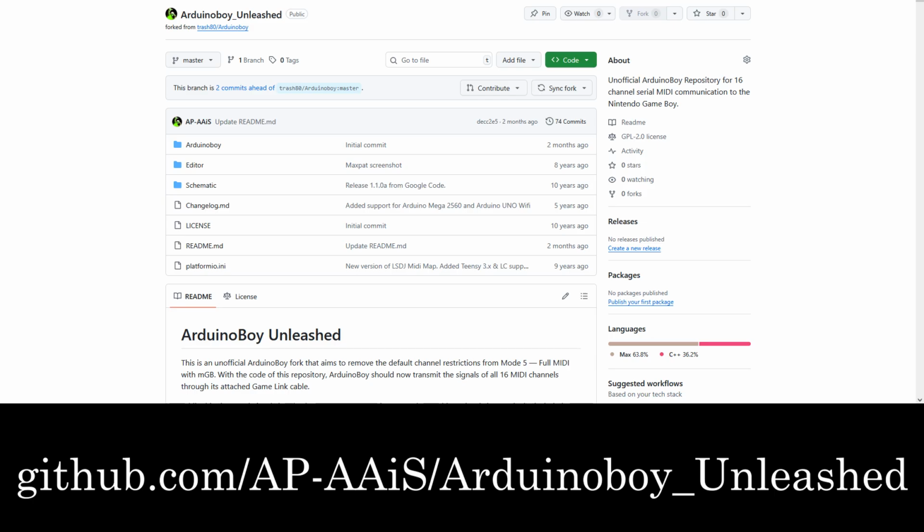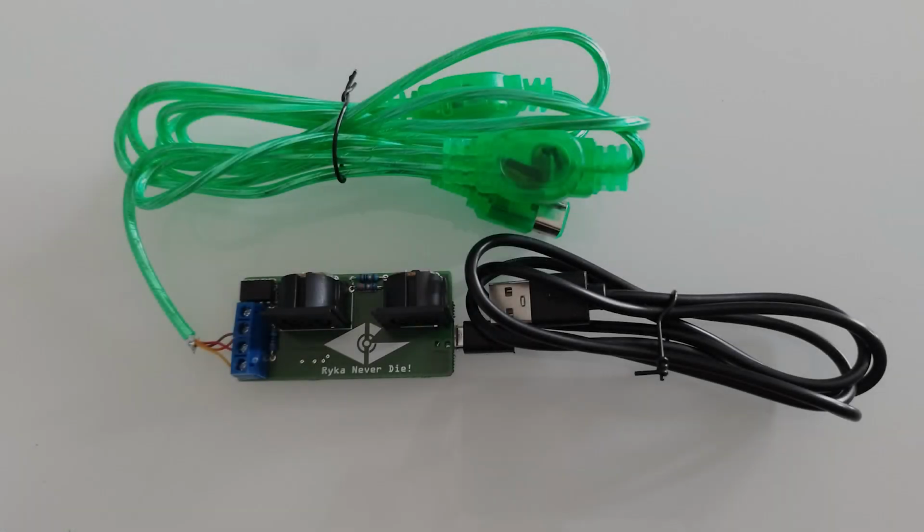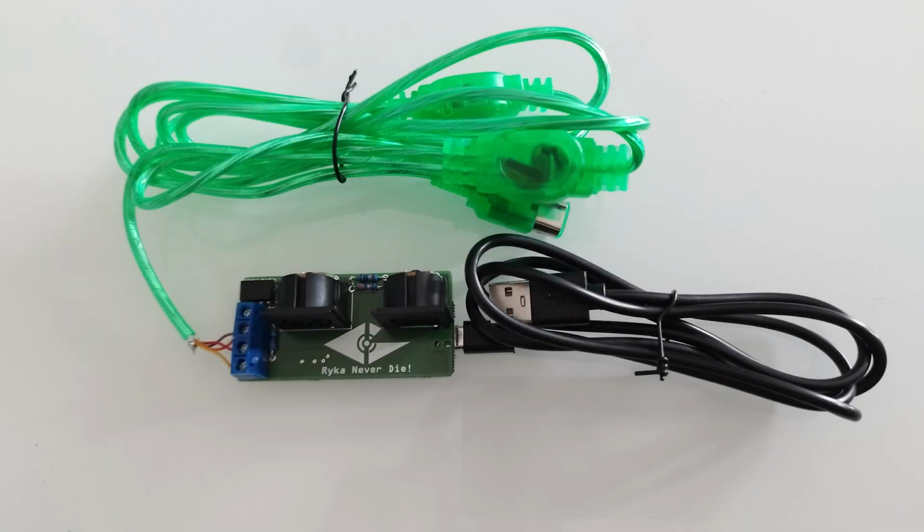With Arduino Boy Unleashed, however, Arduino Boy will send out the signals of all 16 channels regardless of any max editor assignments. Accordingly, you can attach additional GameLink cables to the output pins of the Arduino Boy and then connect more Game Boys running MGB Hydra to those, and you're now able to play up to 16 MIDI channels across 4 different Game Boys. With MAPicoBoy, the setup is similarly simple.